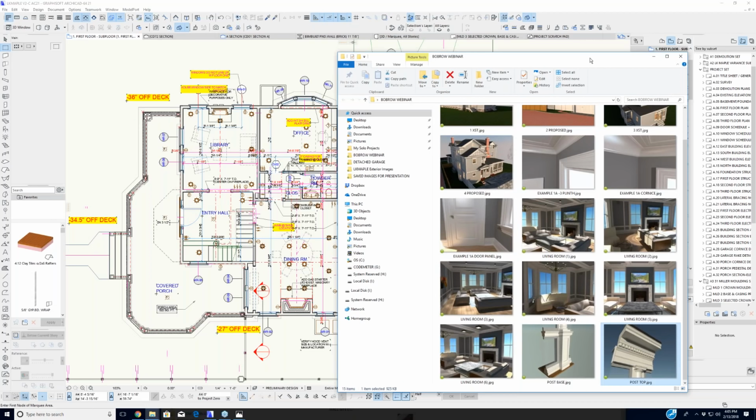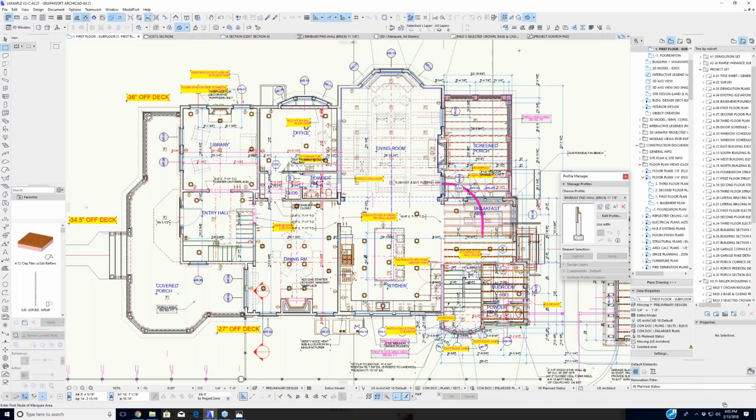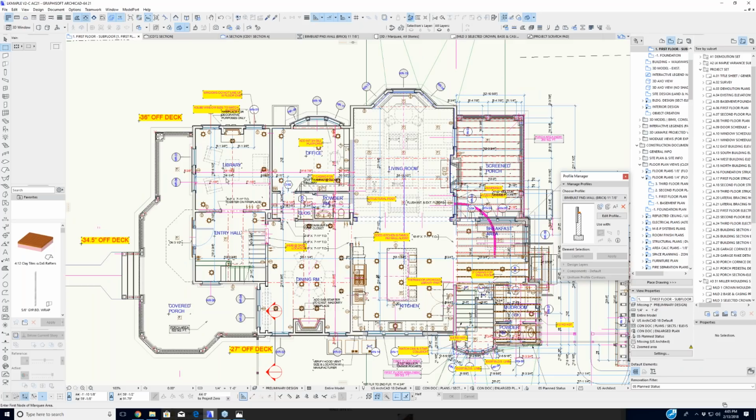So you're in the model and you're going to save something as a BIMX file? Yeah. I would literally say Save As. The question is where the command is, because Eric Zerong was saying he looked under File, Save As, and it wasn't a format available. Are you sure you're in the 3D window? Well, just go to 3D and let's see that. Yep, okay.